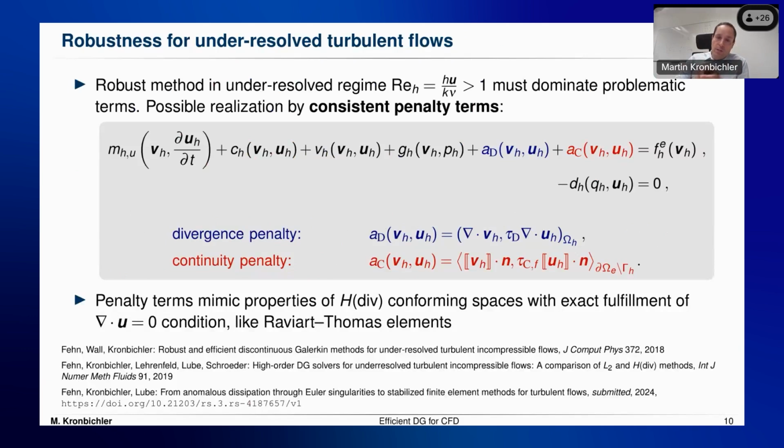There are finite element spaces already out there. There is the classic Raviart-Thomas elements on hexahedral shapes, which have the velocity space chosen such that the velocity divergence is exactly the same space as the pressure space, and then the divergence-free condition actually results in a pointwise divergence-free field. So you don't have discretization errors anymore if you choose Raviart-Thomas.